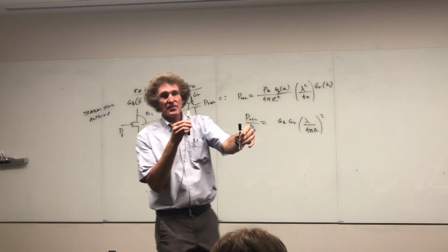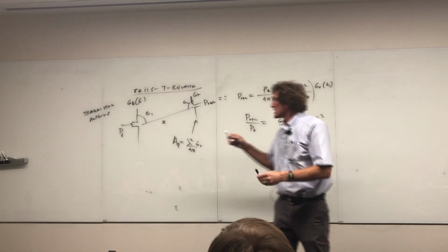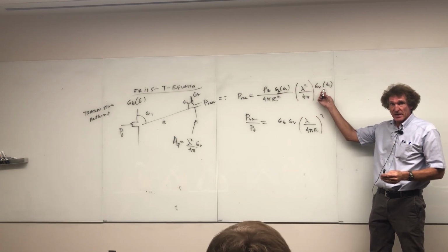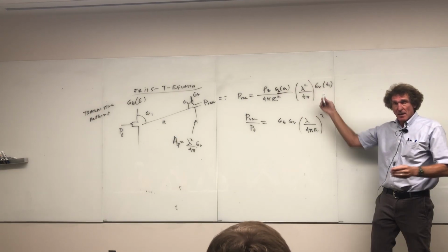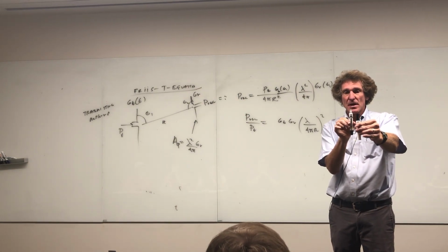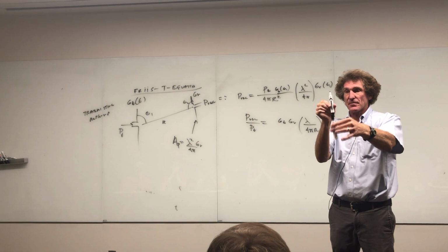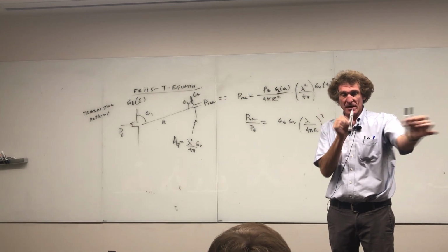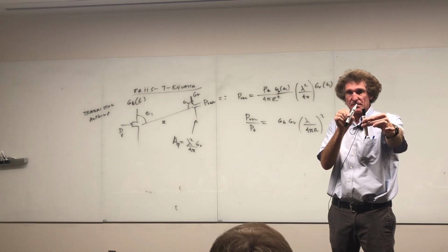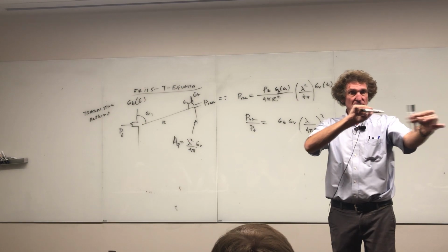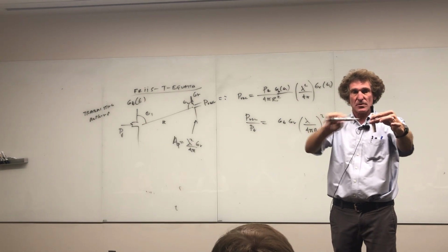All right, here's another thing that happens. Now that you got that down, because that's taking care of this with these gains, right? Because that angle is with respect to the radius vector, correct, class? But here's another thing that happens. This is polarization mismatch. Here they're aligned. The electric field from this one generates a current in this direction on the receiving antenna. But what happens when I do this? All of a sudden, when I get it like this, the electric field from this one is horizontal.